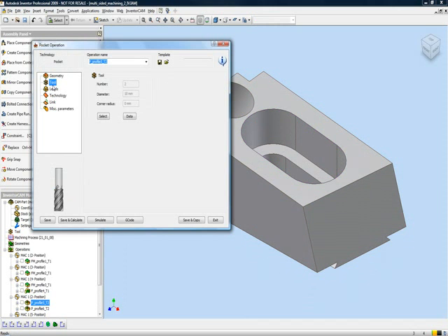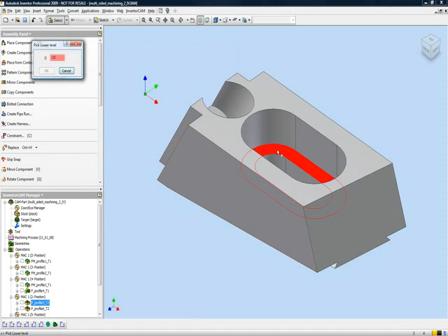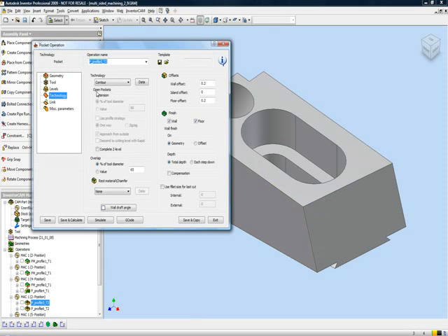The tool that I'll be using will be a 10mm end mill, and my levels, that being my upper level and my pocket depth up until the step itself. My technology, I'll be using a simple contour option, and I'll be leaving 0.2 millimeters on the wall and 0.2 millimeters on the floor. And besides that, I'll also be doing a finish with this tool, both on the wall and on the floor itself.